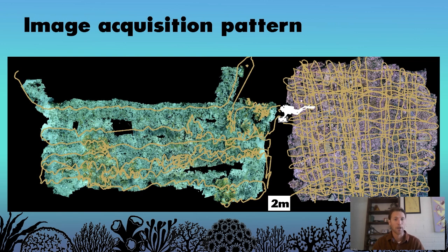While an image was generated in the model on the left without proper overlap in the interior, it suffered from relatively large reconstruction errors. To that point, you will also notice the ragged edges at the plot boundaries. This is an inevitability of large area imagery, as we have to stop taking pictures at some point. And as a result, the pictures on the edges will overlap with fewer other images, resulting in lower reconstruction quality at these plot boundaries. This also highlights that we need to ensure that we maintain a buffer around our core plot area to make sure that it is sufficiently imaged.